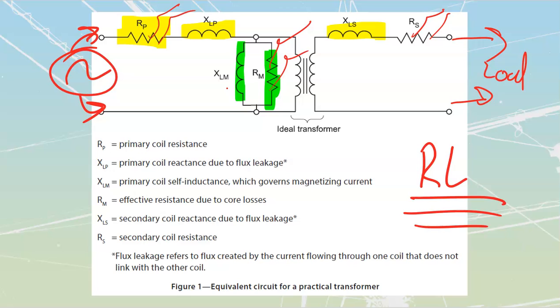We are also going to have another one called our dielectric loss. The dielectric loss is simply going to be the loss that happens inside of the insulation around our conductors, right? The orbitals of that insulation around our conductor. So this center part here is the conductor, but the orbitals around here are going to be changing back and forth because I'm going to have an AC current going through here. So there's going to be a tiny amount of heat given off of that.